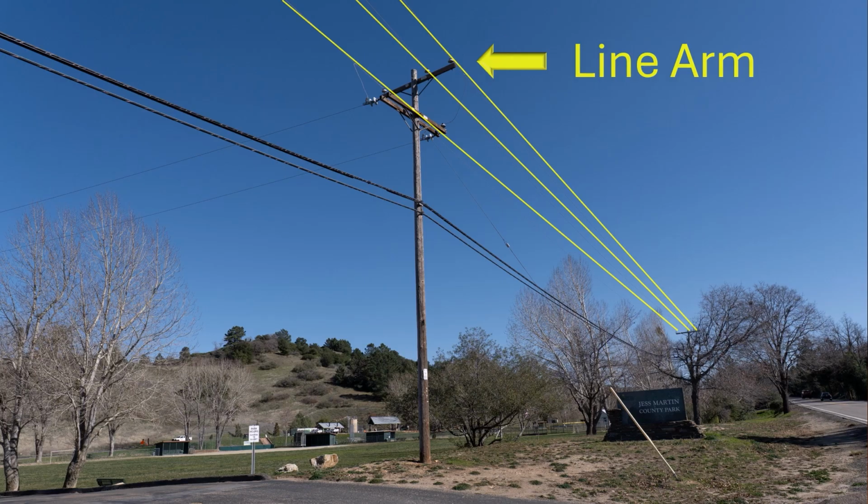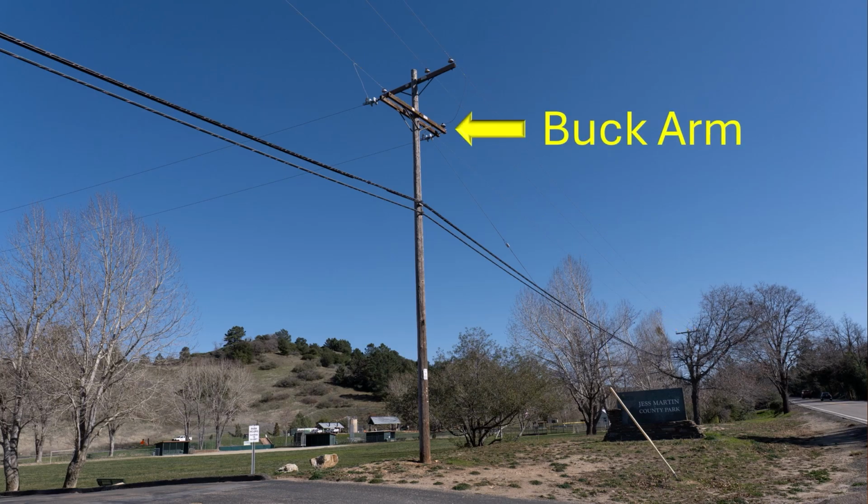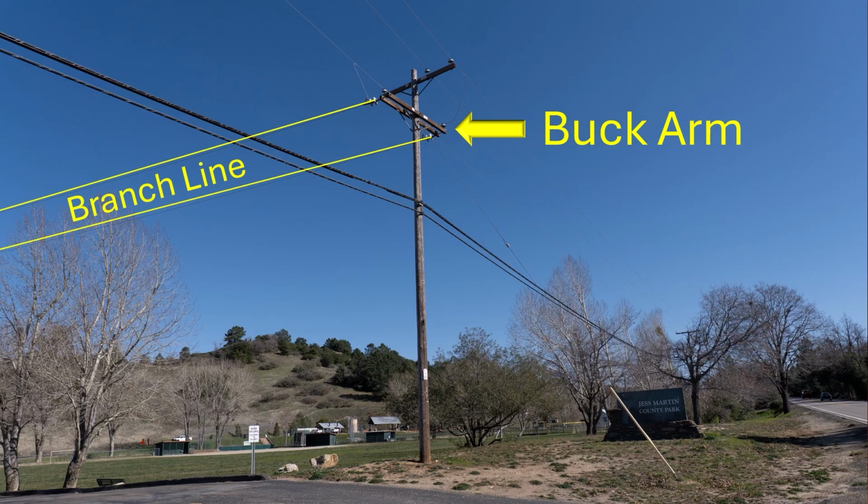Just below the line arm is what's called a buck arm. A buck arm allows a branch line to be created by extending another set of conductors in a direction perpendicular to the tangent conductors on top. This buck arm is just a dead-ended arm with a guy and anchor, just like in our example. The total load on the pole can be determined by adding up all of the loads caused by the tangent line arm and the dead-ended buck arm and anchor.